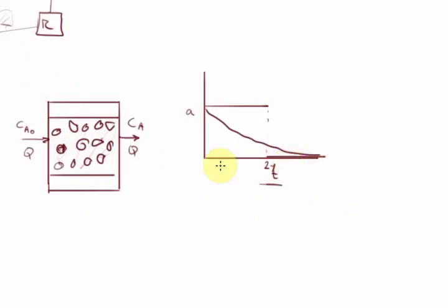We are going to regenerate, but what are we going to do continuously, given that we are going to lose activity over time? One thing we could propose is, well, let's change the temperature. If we change the temperature progressively, if we increase it progressively, then we are certainly increasing the primary reaction that's going on here. Of course, we've got some primary reaction that we are trying to catalyze. Even if it's a simple one like this, A goes to B, let's say the reaction rate is kCa, so it's a simple first order reaction.